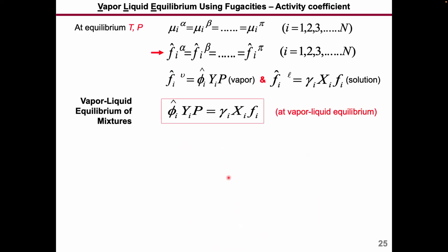All right. So finally, when we talked about the vapor-liquid equilibrium for a real mixture, we need to use fugacity, instead of involving just the ideal pressure. For equilibrium at constant T, we know the chemical potential has to be the same, so basically this has to be true.